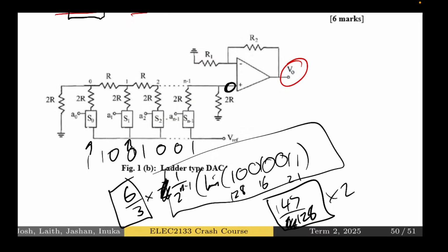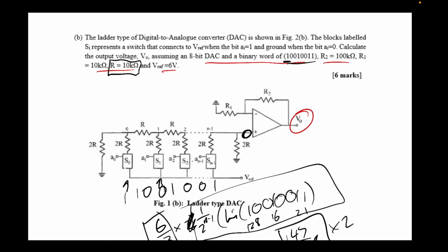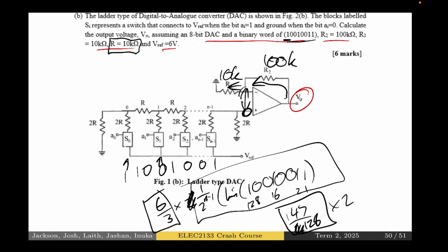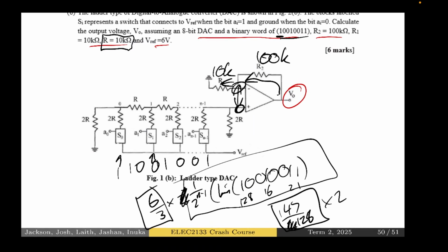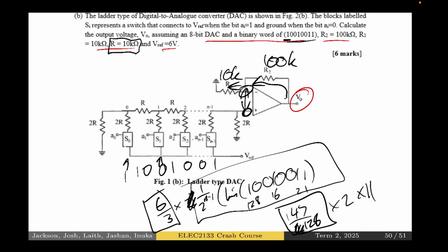Okay. So that's V plus. Then we go ahead and we do the non-inverting op amp. We know it's a 100K to 10K, and if we ever get in trouble and forget the formula, we can just recognize that, okay, same current going through, we know these two voltages are the same, and oh my gosh, same current through 10 times the resistance just multiplies it by 10 to that point, so total, you get times 11, essentially, because there's 11 times the resistance for the same current. So then times 11, and that would give me my answer as V out.